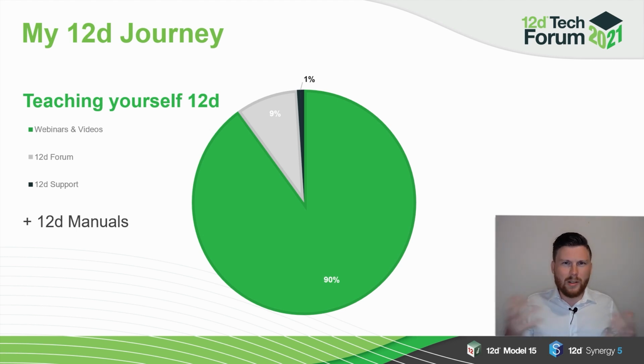And it wasn't until about 3 months in or something I realized you could use the middle mouse button or the scroll wheel to select things. And just taking that one step out of it just made life so much easier, so much faster. And there's lots of little tips and tricks like that in the 12D manual on snapping or drafting things that can really help you use 12D really efficiently. Or that's what I've found at least.